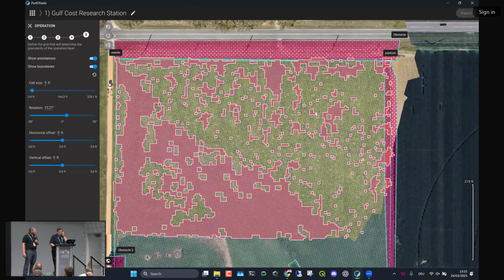That's true both for a ground rig and for a spray drone, because that reduces sampling issues. We are still operating on a grid, and if a GPS receiver is on a diagonal of the grid or a part of a grid cell, then it can spray something which it shouldn't. So try to align the grid with the main application direction.